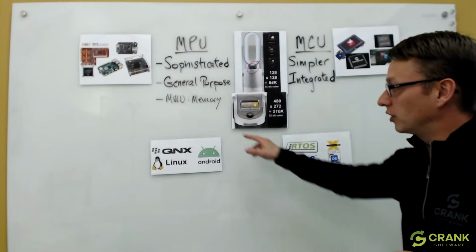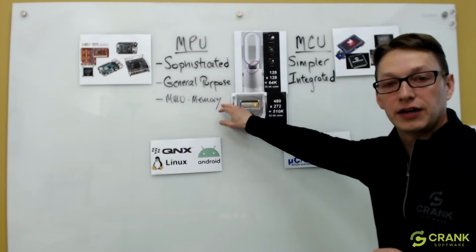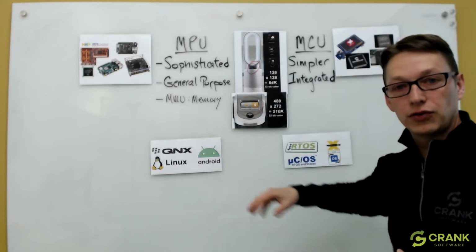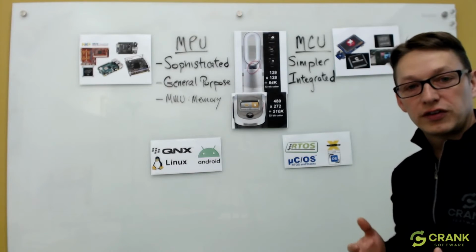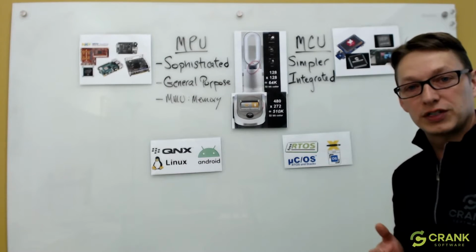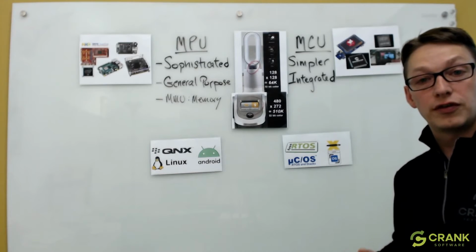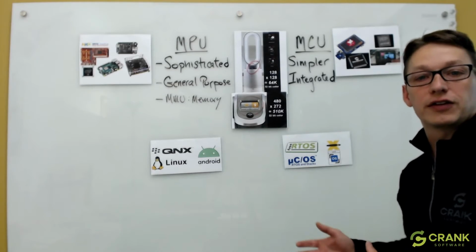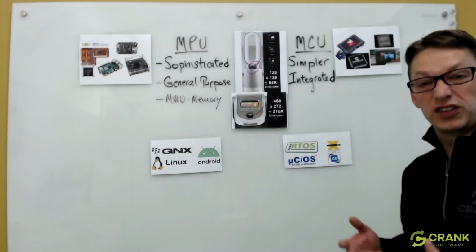And a lot of that has to do with this notion of what kind of memory access is being provided and what the system looks like in terms of its configuration. QNX, Linux, Android, these are all systems that typically rely on a process model, with processes executing independently from one another in a memory-separated space, so that the system can be a little bit resilient in terms of component failure. One component failing or writing into a block of memory doesn't actually affect the other components. This is an important consideration for product resilience, right?